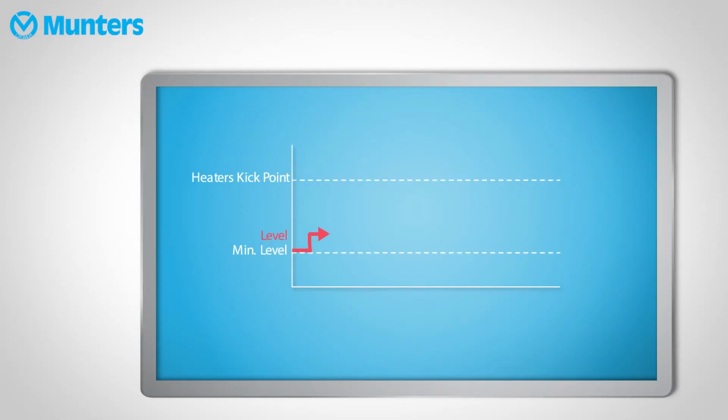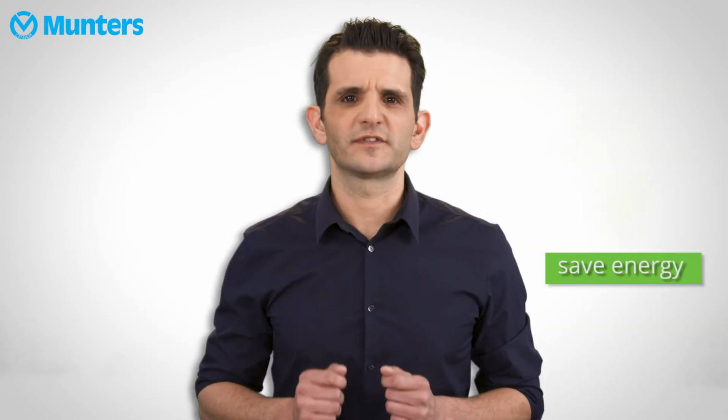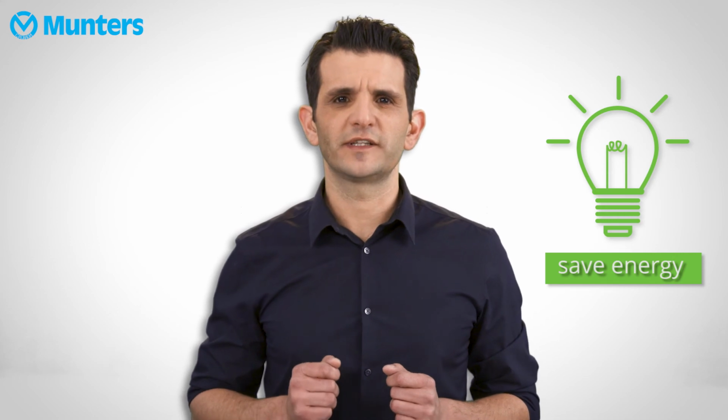By definition, a precision controller drops to the minimum level immediately when the heaters start. This means that if the controller, for example, is at level 10 and the minimum level is 3, as soon as the heaters kick in, the levels would immediately drop to 3. This was designed in order to save energy and prevent heaters running with excess ventilation. This mostly happens when you set a heater temperature very close to the target temperature.